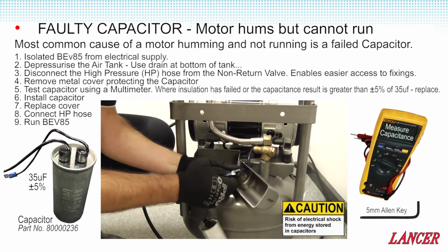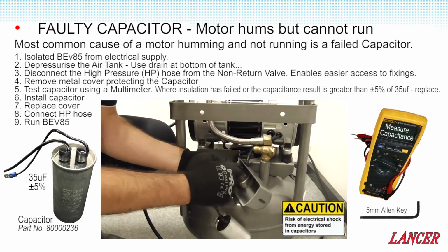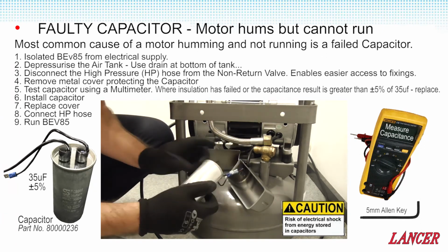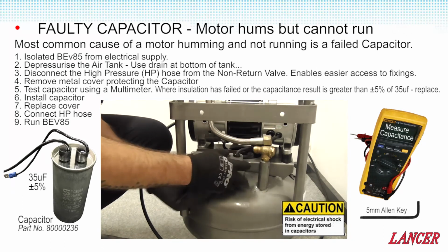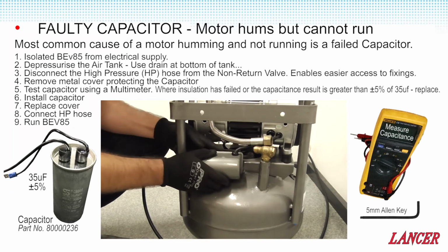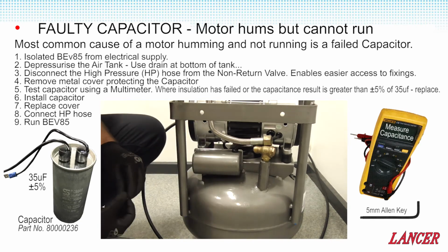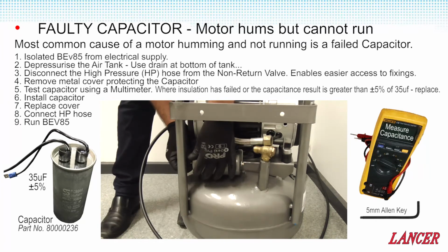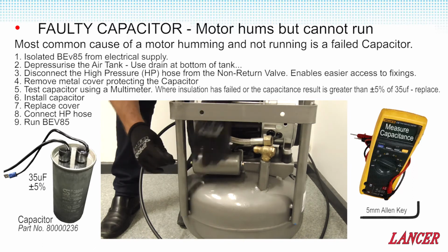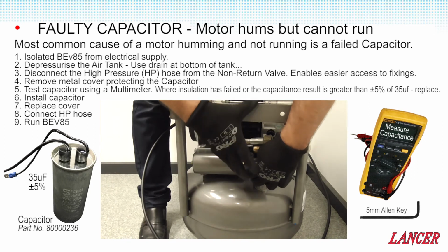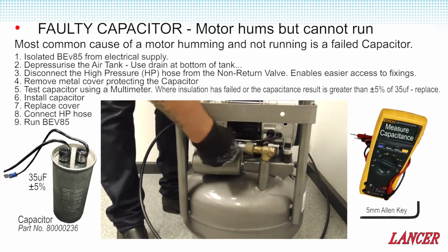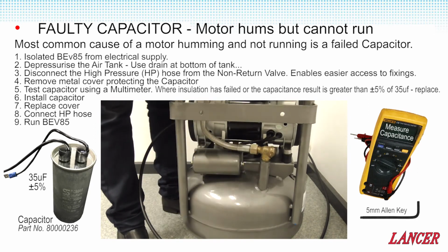Then reinstall the capacitor. Replace the cover. Connect the high pressure hose and then run the unit again.